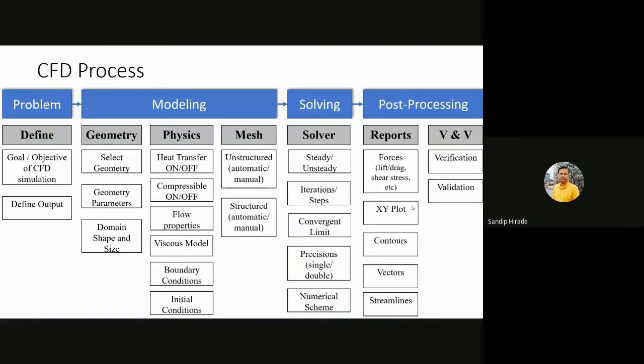In the physics, you have to consider what your input data is, whether you have sufficient inputs, that is, your boundary conditions. And then when you start solving the problem, the partial differential equation, when it is converted into numerical form, requires initial conditions to start with. The initial condition is nothing but just a guess. The initial conditions are also governed by, or can be derived from, the boundary conditions.